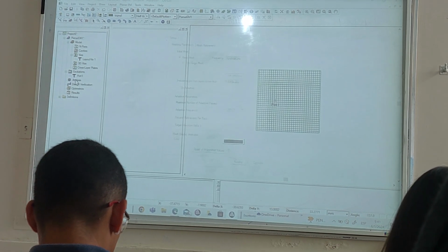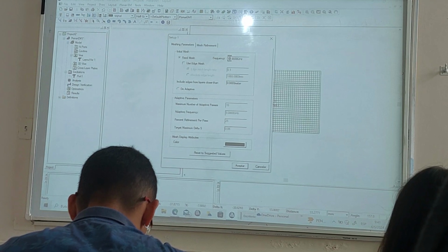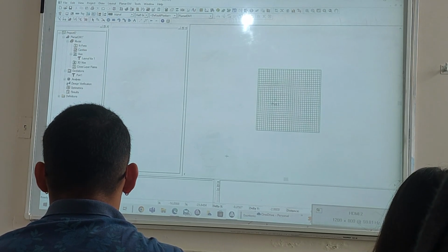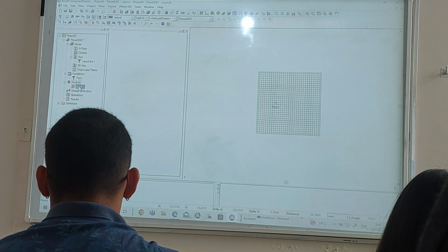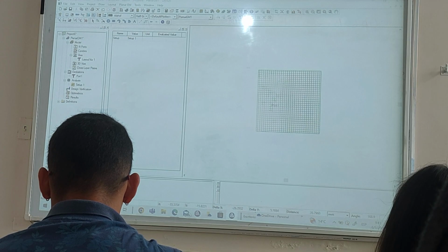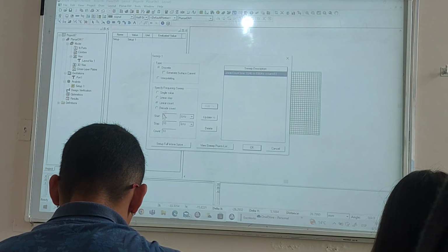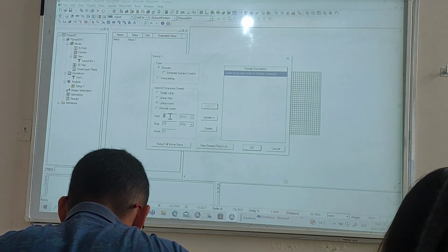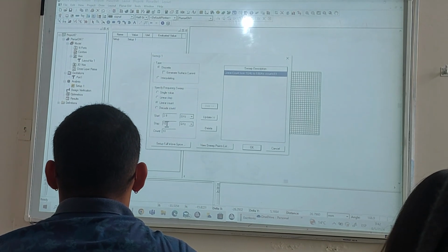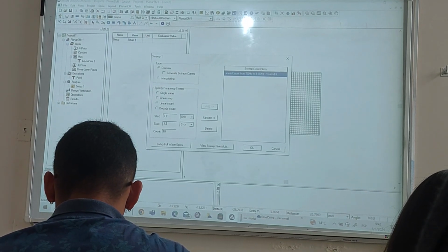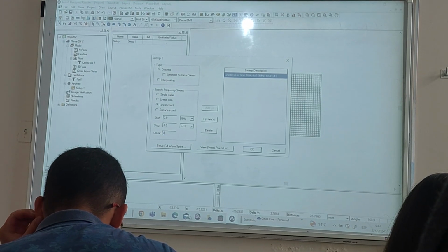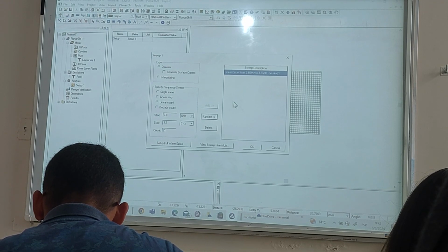We have to do the analysis. The analysis was at 3 gigahertz. And we need to define the sweep. We use from 2.8 until 3.2 because remember that the central frequency is 3 gigahertz, with 21 frequencies.